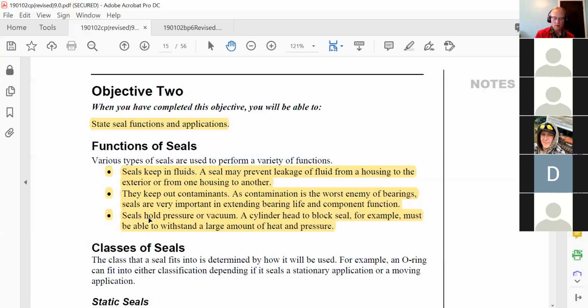What do we have on hubcaps, trailer hubcaps specifically, on drive axles, on transmissions? What do we have even on engines to prevent that? Vent lines. Yeah, we have vents, right? In our engine, the crankcase is vented. I mean, it's not venting to atmosphere anymore.